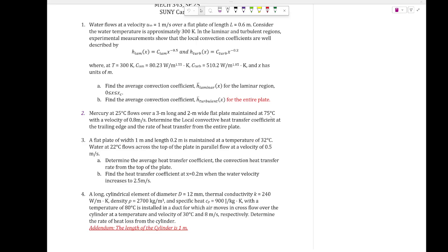You know that. When you do the experiment and get all the data, find the H value by using the slope and everything that I was saying, you should see different values of H for all 5 cases. When you're doing natural convection, the H value should be very low. When you're dealing with very high speed of air, you should expect the H value to be very high. If you're seeing those trends, you should know you're doing the right thing.